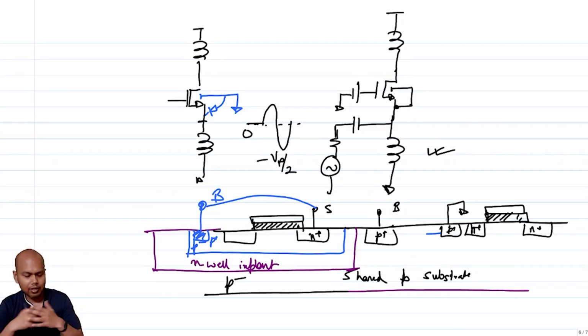Granted, the value of the inductors that we require might sometimes become prohibitively large, and because of that, what generally people tend to do is, if at all that is required, you can put an off-chip inductor, right? So you can put a large off-chip inductor and do not burden the chip with large on-chip inductors, which can take up a lot of area, and that is actually done.